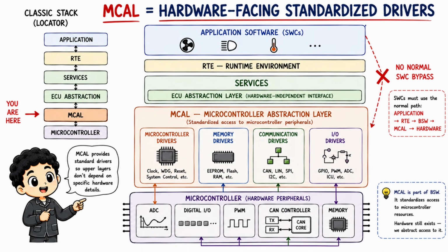Closest to the microcontroller is MCAL, the microcontroller abstraction layer. This is where standardized drivers access microcontroller peripherals and hardware resources. Depending on the ECU, that can include I/O drivers, communication drivers, memory drivers, and microcontroller drivers. ADC, digital I/O, PWM, and CAN driver concepts live at this hardware-facing end of the stack when they are part of the configured system. MCAL does not make the hardware irrelevant. It creates a standardized software boundary around hardware-specific access, so the upper basic software can be less dependent on a particular microcontroller family.